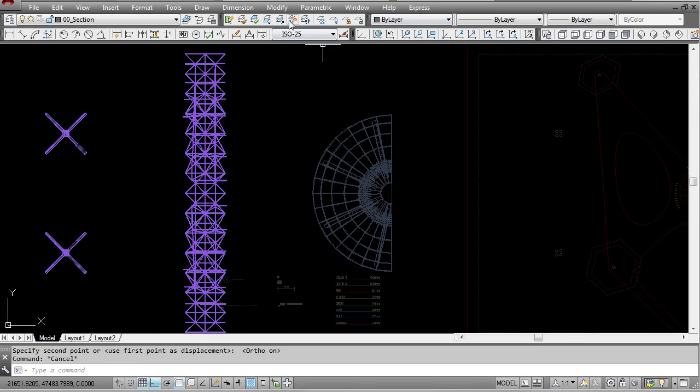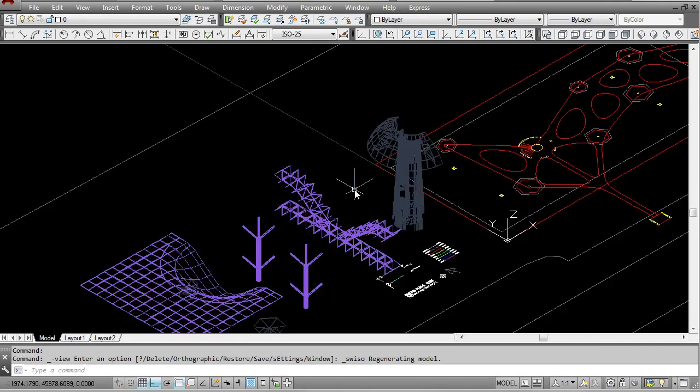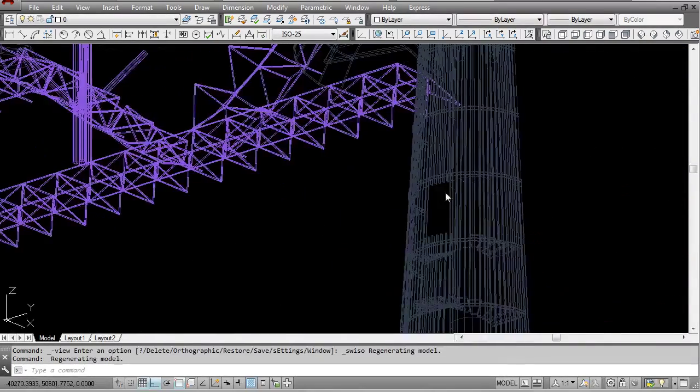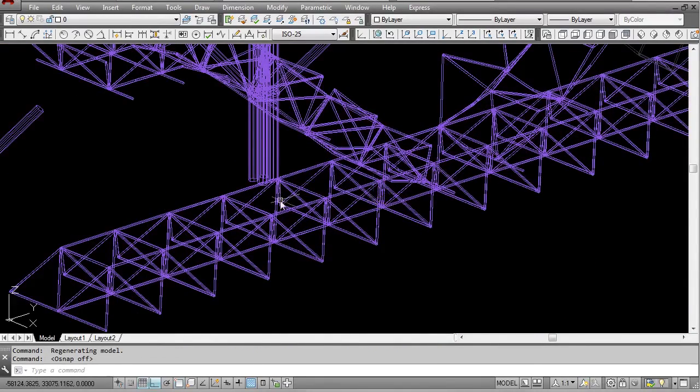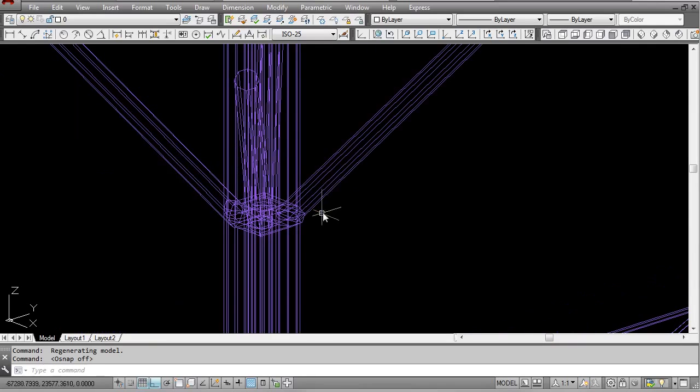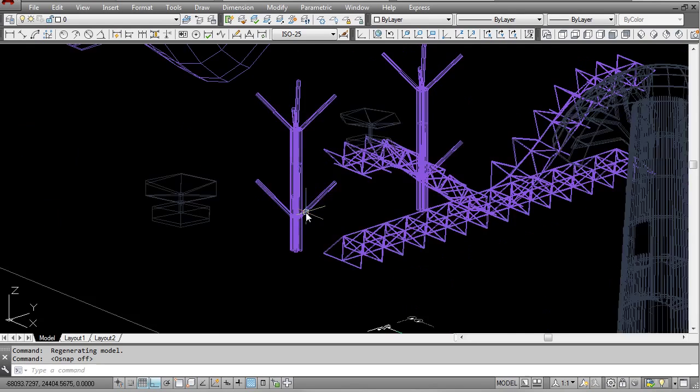Now, when it comes to all of these objects, they're going to be a little bit tricky to work with, because if you have a look at them in 3D, they are going to require a hidden line view in order to work properly. So for example, all of this, we have a lot of three-dimensional objects that if we use the flatten command, they would basically become all squashed, very much the way we would make something planar in 3D Max.